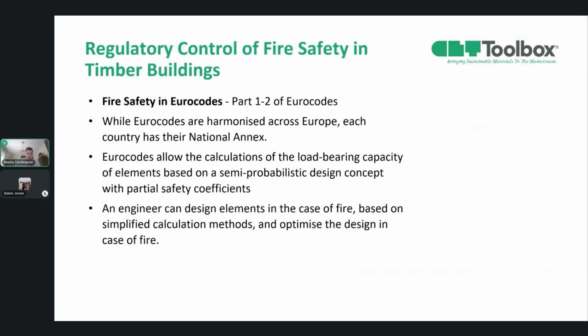Part 2 of Eurocodes addresses the performance of structures in fire. And while harmonized across Europe, each country allows adjusting certain parameters through national parameters and nationally determined parameters. Eurocode allows the calculation of load-bearing capacity of elements based on the semi-probabilistic design concept with partial safety coefficients.